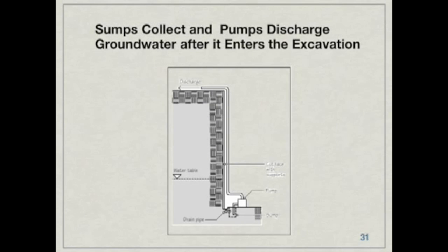Now, sump pumps or sump pits is something that all of us, I'm sure, have encountered at one point or another. Probably have used them in our basement if we're unlucky enough to have our basement flood from time to time, as I have. So the way that this works is simply you create a pit within the enclosure of the excavation. The bottom of the sump must be sufficiently below the final elevation of the excavation. Then as the groundwater percolates in from the soil, the sump just grabs it, pumps it out, and discharges it to an appropriate location.